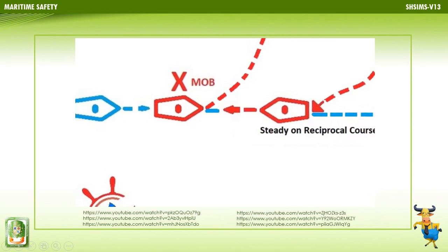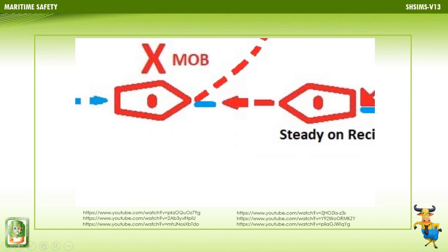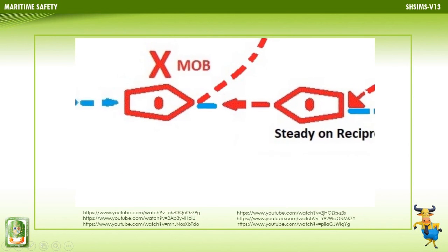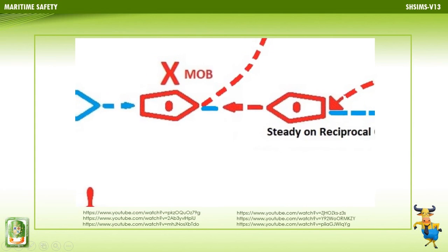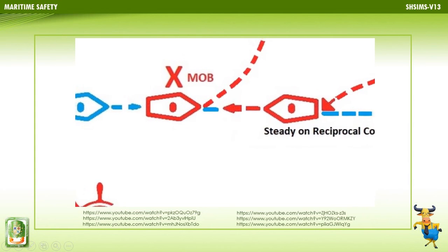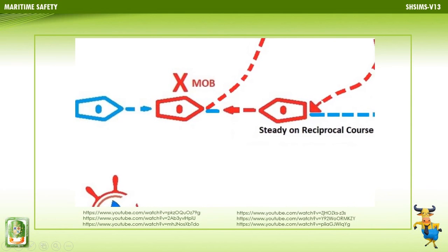The helm is then reversed with the same amount of helm applied the opposite way as was used in the initial turn, for example 1 full turn of the wheel to starboard, then back to midships, and 1 full turn of the wheel to port, until the vessel is on the reciprocal of the original course. The vessel turns and initially describes 1/4 of a circle. When the helm is reversed, it then describes 3/4 of an identical sized circle.